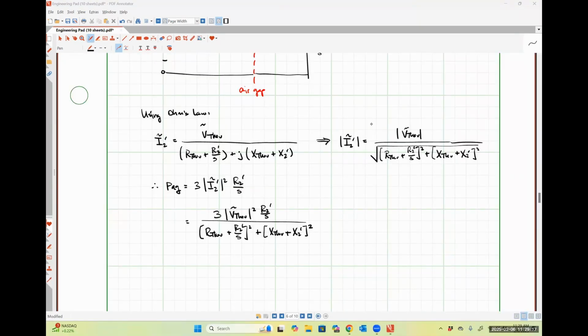About one of the claims we made. So we said since RC was vastly greater than jXM, we simplified and cut out RC, right? Where I'm confused is then we made similar statements saying that if R1 squared was significantly less than (X1 plus XM) squared, we got rid of it. So we're not getting rid of it in our model, we're getting rid of it in our math to make the way that we calculate Z Thevenin a little bit easier.